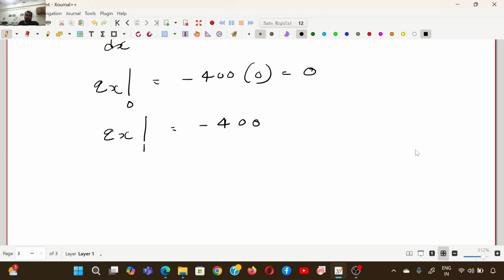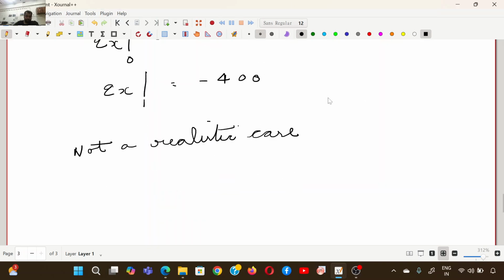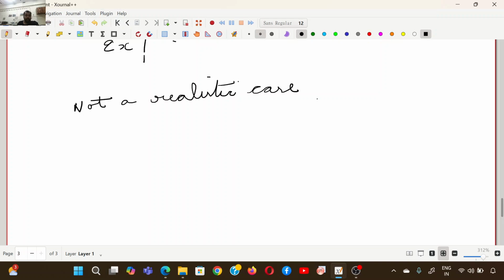In between the two boundaries there has to be some source term that can explain this discrepancy between the heat flux at this end and that end, and also the nonlinear profile. So no heat generation means T should be linear.